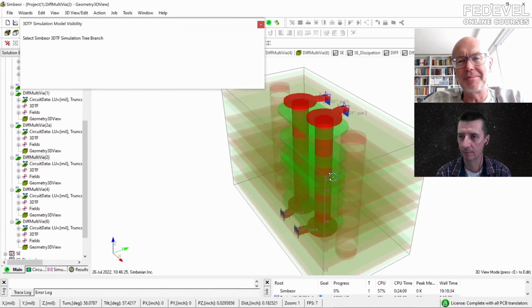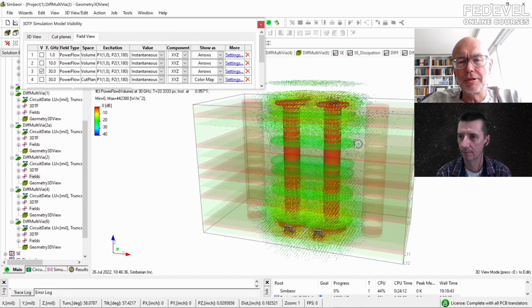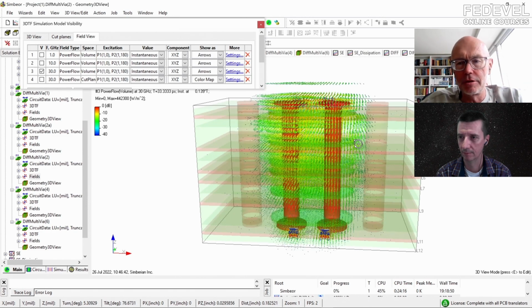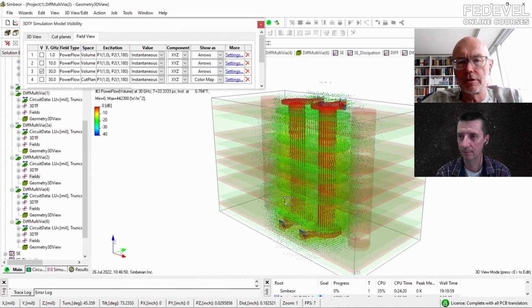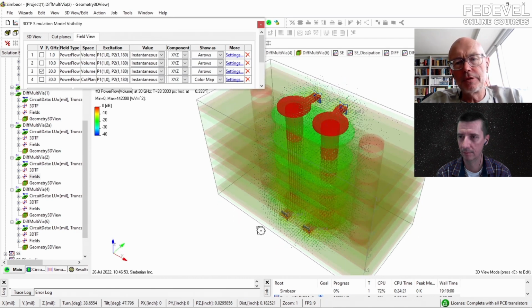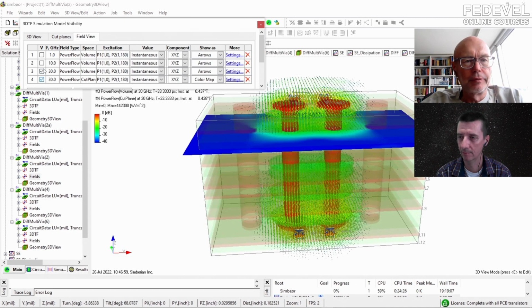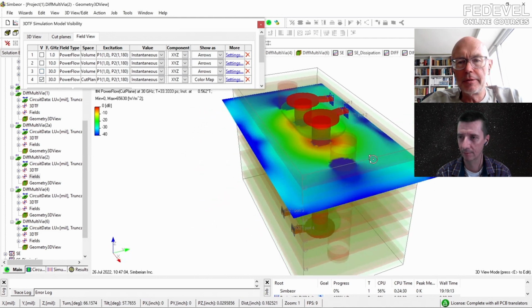I saw some expert recommend it like this and so on. But what if you put it like this? Again, this is 30 gigahertz, so immediately jump into 30 gigahertz. With differential vias, we obviously have much higher bandwidths, even without stitching vias. It's still kind of functional at much higher frequencies compared to single-ended, but they still have the problem. So right here, we see that those vias are preventing the radiation. You can clearly see it. It's still happening. They're still kind of reflecting.